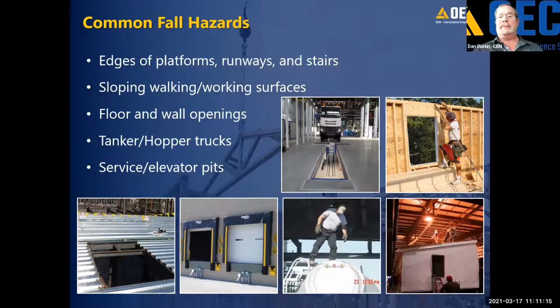One of them is that any pit or shaft is considered a confined space. And if it's more than 5 feet in depth and somebody's going to be working in it, I have to have a mechanical means of retrieval available. They have to be protected from falling in the first place. And I also have to be able to get them out if they get in.